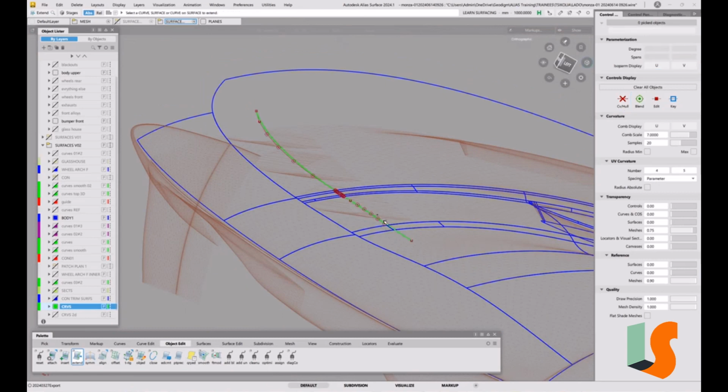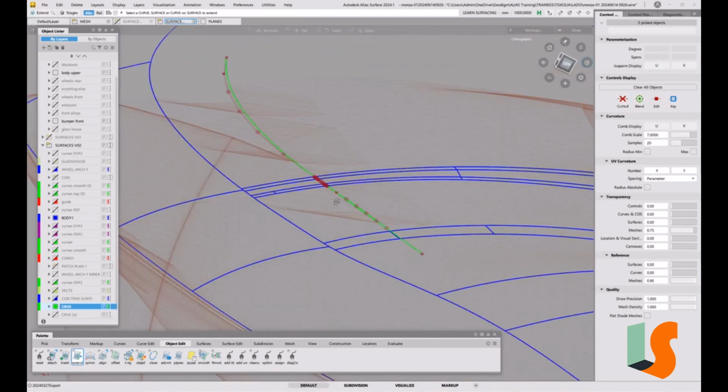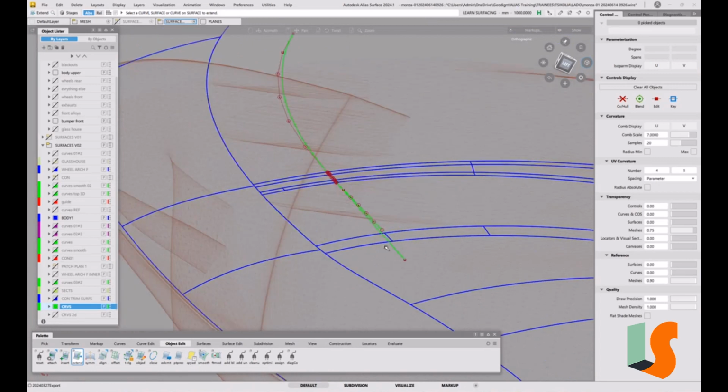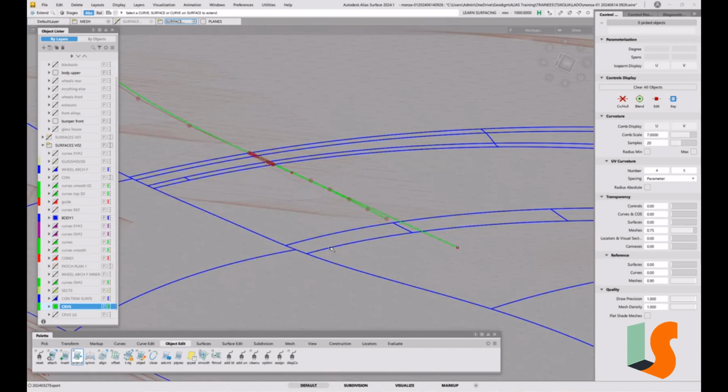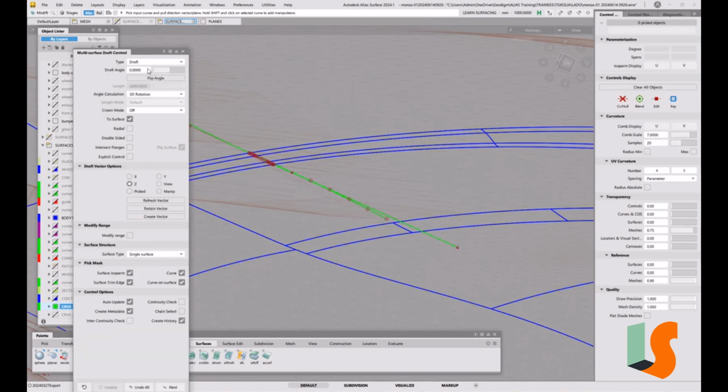So we'll do that. And then what we'll do, so I can rotate that around and try and get best fit. That's one option. The other possibility that we can do there is we put in a draft surface off that. So if we take a draft surface and we put it in Z and I'll put history on here. And so we just start off with that. It's got 2 surface on, so we need to switch that off so it actually works. And I'll put in a sensible length like 100 or something, maybe even less than that, 50. And we've got history on there, so we can rotate this.